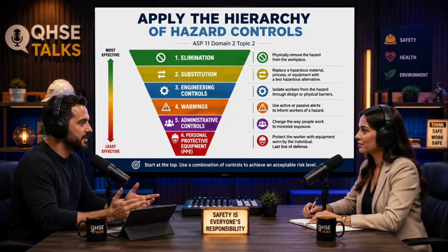But it is crucial to understand why it is elimination. Because you haven't actually changed the brazing process itself, right? Exactly. The worker is still using an open flame. The hazard of the open flame still exists. However, by moving the operation, you have physically removed the ignition hazard from the fuel source. The specific risk of a catastrophic dust explosion has been entirely eliminated from that specific task. Yes, you dismantled the necessary conditions for the disaster.